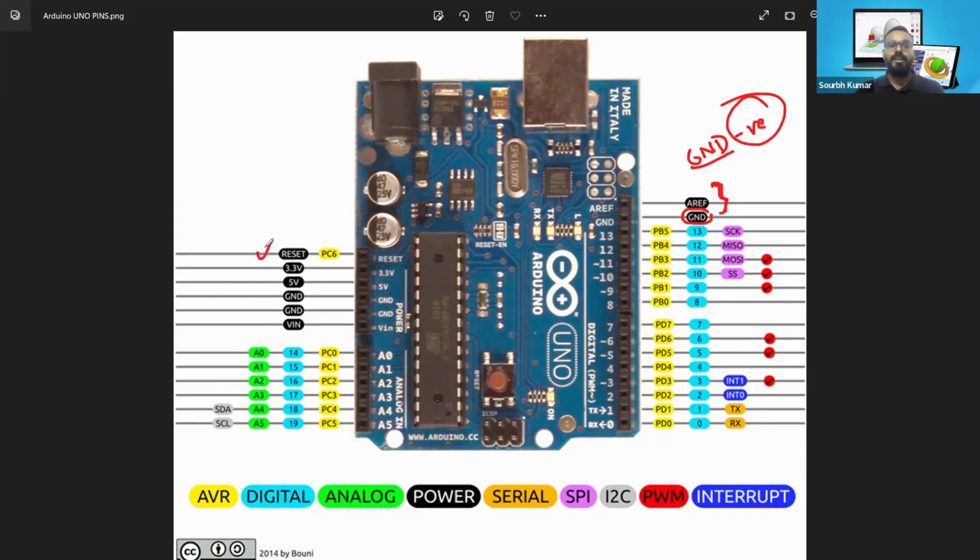One more thing in here is the reset pin. Okay, let me show you one thing. Here itself we do have one of the reset buttons, right? Let me draw one of the symbols to represent the reset button. The reset button will obviously have two terminals. Right now it has 4, but only 2 of them are required. So one will be connected to the GND and the other is connected to this particular reset button.